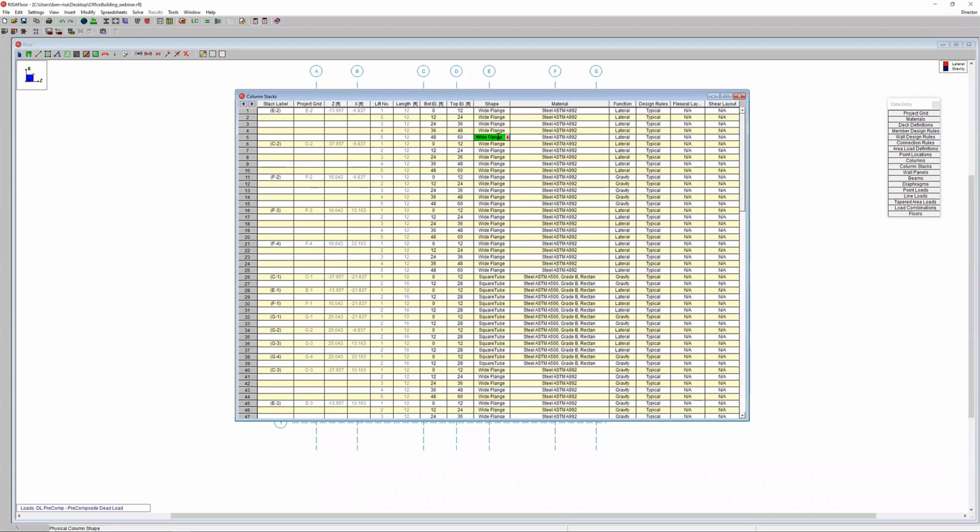You could comment out different shapes to say, you know what, I don't ever want to design a column that's a 4x13. You could do that if you wanted to, or we do have some pre-built specific lists built in. I'm going to use one of those for our lateral columns. So in this particular table, I'm going to say I want to fill block. Basically, I can go ahead and type, and then I'm just going to type in WF space 10.